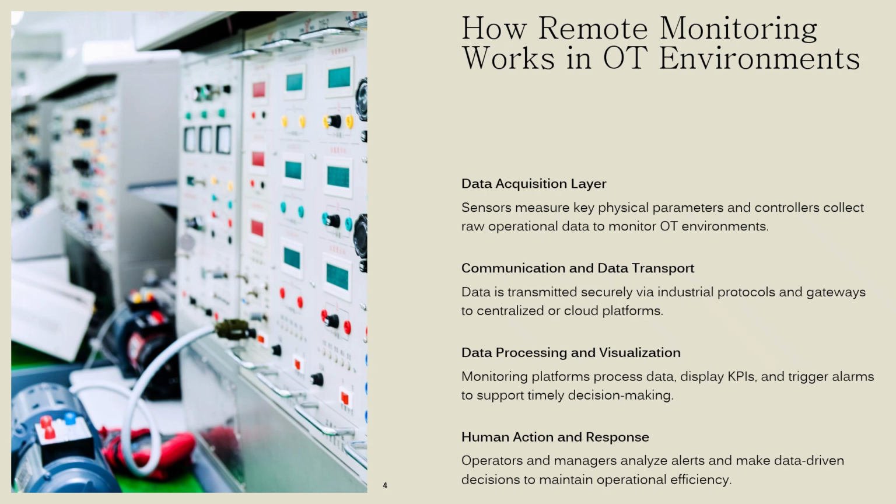Dashboards display real-time status, trends, and key performance indicators (KPIs), while alarm engines evaluate data against thresholds and generate notifications via HMI pop-up, emails, SMS, or mobile apps. Advanced systems apply analytics, machine learning, or rule-based logic to detect anomalies and predict failure.